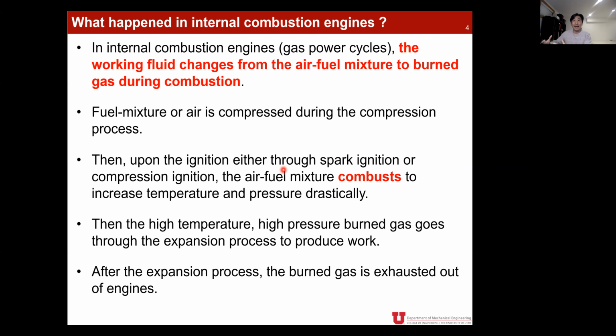Then your burned gas after combustion has very high temperature and very high pressure, and that is so high and intense that it's sufficient to rotate your shaft or move your piston back and forth. Then it goes through the expansion process, and this expansion process is the key process that produces work. And after the expansion process, you still have burned gas inside of your engine that needs to be exhausted. This exhaustion process follows the expansion process.